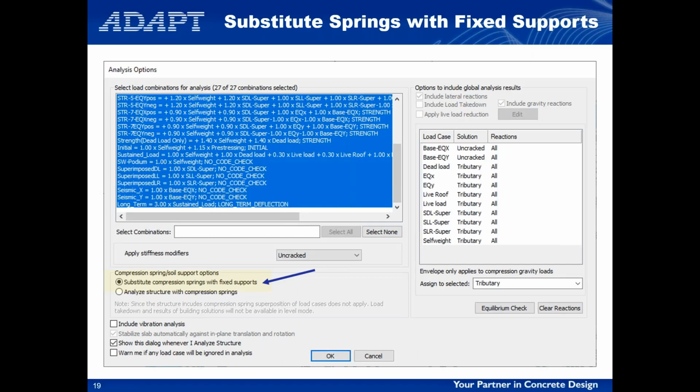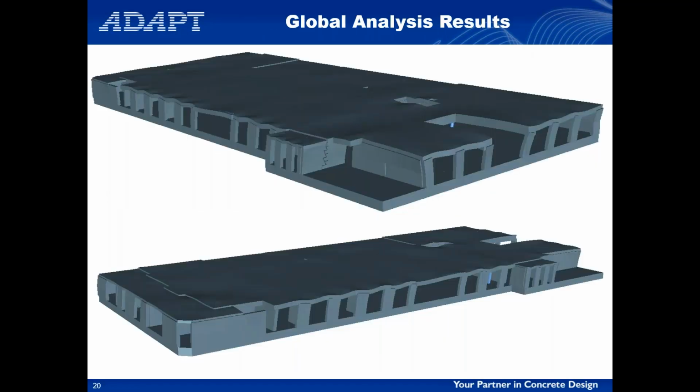Once we've done that analysis, here are some images of having run this concrete podium box. And now remember, the superstructure that we don't see is not explicitly modeled in Builder, but we've applied all of the couples and the base shear. So you can clearly see the lateral deformation in that structure.